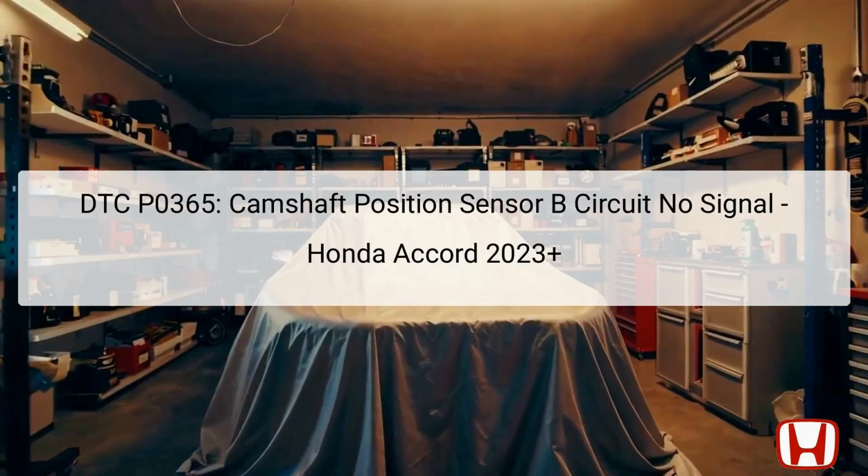The Diagnostic Trouble Code, DTC P0365, signifies an issue with the camshaft position, CMP, sensor B circuit, indicating that no signal is being received. The CMP sensor plays a crucial role in monitoring the position of the camshaft, which is essential for proper engine timing and operation.